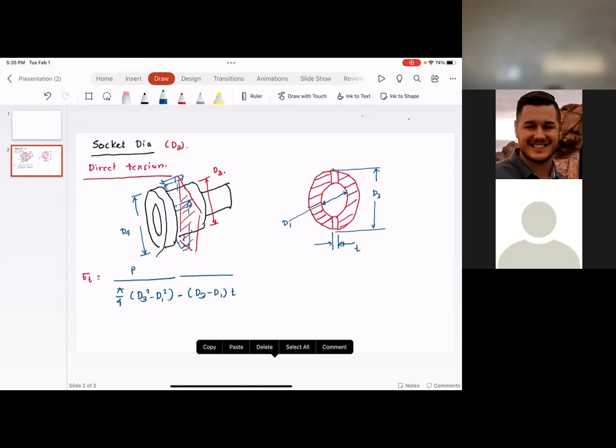And remember, from statics and dynamics, you looked at the friction. So basically, that taper dictates the amount of force that you need to apply on the cotter to dismantle it. So depending upon the type of joint you want, that taper is given in the design data. So that is how. Yeah.